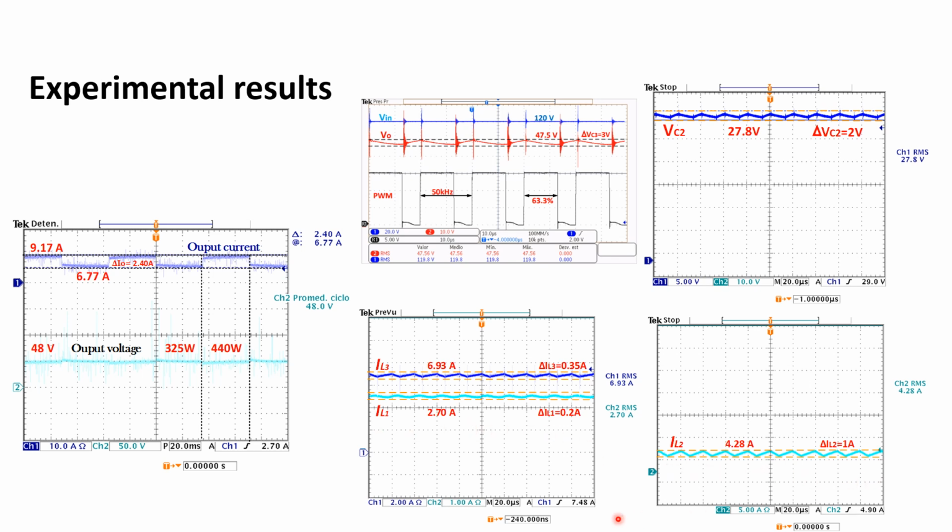We can observe load changes from 325 watts, the operating point, to 440 watts, the maximum demand point, which allows the platform to perform the test. It is also worth mentioning that for DC microgrids, disturbances traditionally occur at low frequencies due to the types of residential loads, which is why this type of controller was chosen.